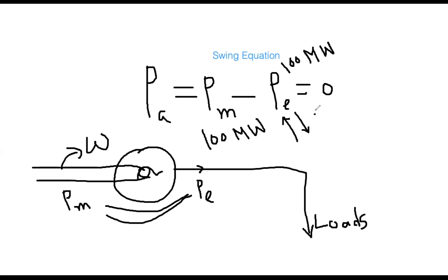No. What result will you be getting? Either you will get some positive value, or you will get some negative value here. There will be some number here because your P_m is fixed. Now, if the result is positive, meaning that P_e is somewhat less than P_m, it is called the accelerating power.